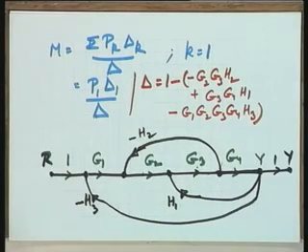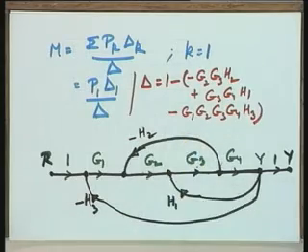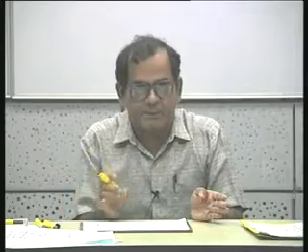All the independent loops, by independent loops, as I explained, means that every loop has at least a node or a branch different from the other loops. Okay? Now, I need not take a plus sign here, because you find that there are no pairs of non-touching loops. Out of these 3 loops, you take any pair, any combination, all the possibilities you try to exhaust, and you will find that a node or a branch is definitely common. You cannot give me 2 loops where a node or a branch is not common, and therefore, there are no non-touching loops. This definition needs your attention, please, because in this particular case, that is the point.